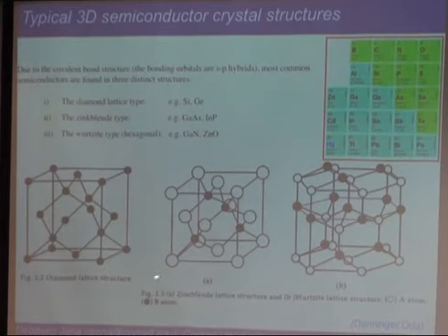And some of those crystals do crystallize in the same form, the zinc blende structure, and some of them go in the wurtzite structure. This is obviously longer in one direction, and it has a hexagonal symmetry. These are cubic symmetries. This is a hexagonal symmetry. And gallium nitride and aluminum nitride are typically in this crystal structure for nitrides. And also zinc oxide. Zinc oxide is a group 2, zinc, and oxygen is group 6. So 2,6. Sorry, zinc oxide is a 2,6 semiconductor, not a 3,5.